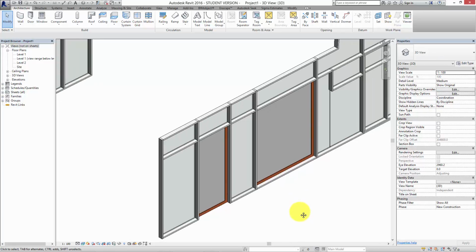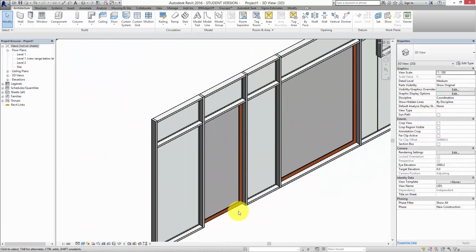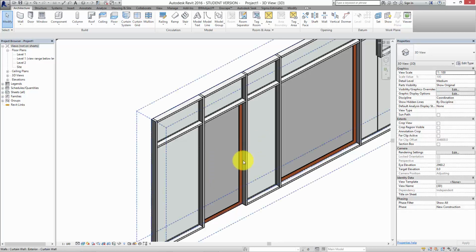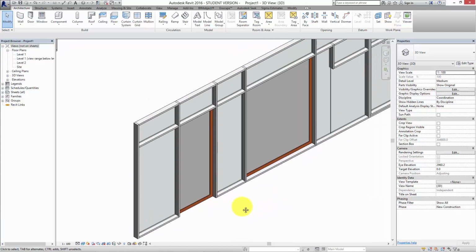All right. So now we have, let's say it's a door. It looks like a door. So let's assume it's a door, this panel that we're making. I want to make a door handle for it because I've decided I want to put an extreme level of detail into my model. So the easy way to make an addition to something like this is not to make it directly in the panel family itself. It's to make it outside as a separate family and then insert it into the panel family. So if you're going to make a door handle, the best one to use is probably the face-based generic model because it automatically sticks to any surface.